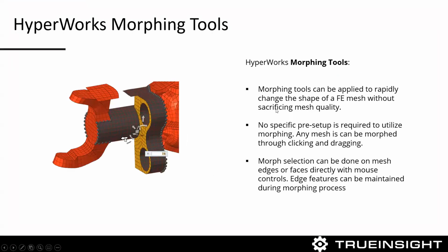So, reviewing the workflow: set up your geometry, make sure you have good geometry, and then go through the quality tools within HyperWorks HyperMesh. Obviously this is just the tip of the iceberg. I couldn't show you every single feature, but these are common things I'll do: check my quality and then manipulate elements accordingly. One of the last things I'll do from a workflow perspective is morphing. Again, this is super powerful and other CAE tools don't really have these capabilities.